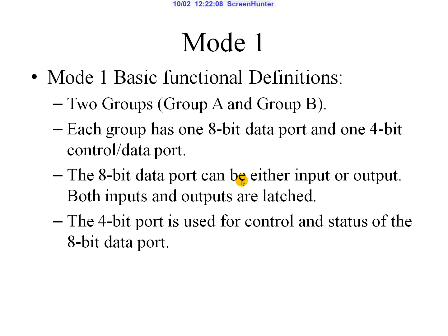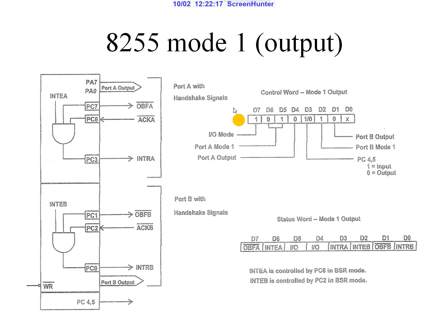The 8-bit data port can be either an input or an output. Both inputs and outputs are going to be latched. The 4-bit port is used for controlling the status of the 8-bit data port.